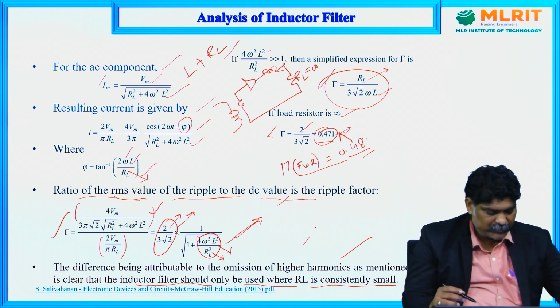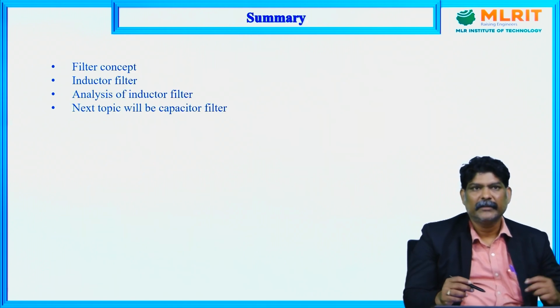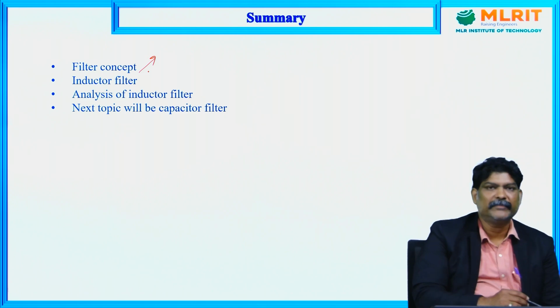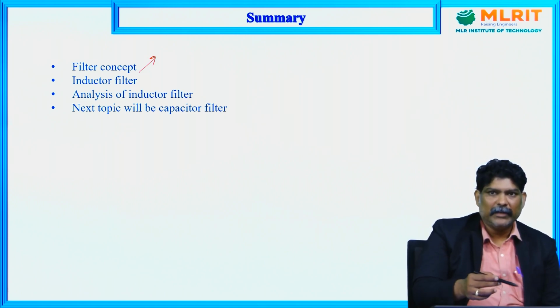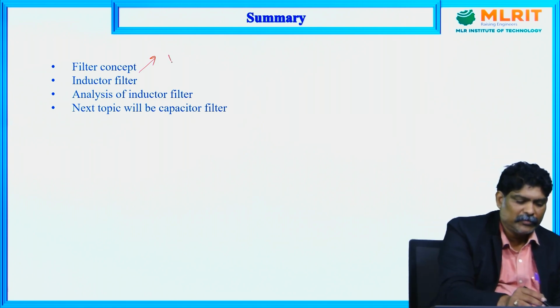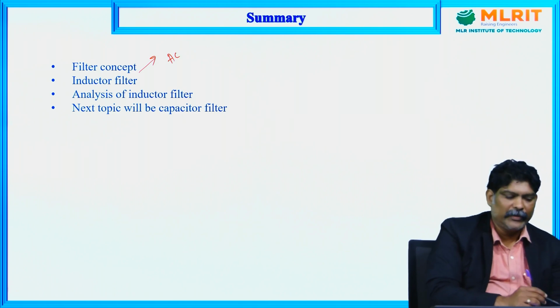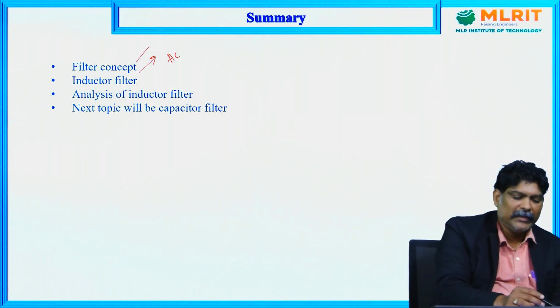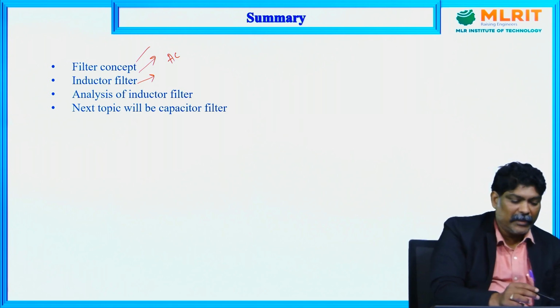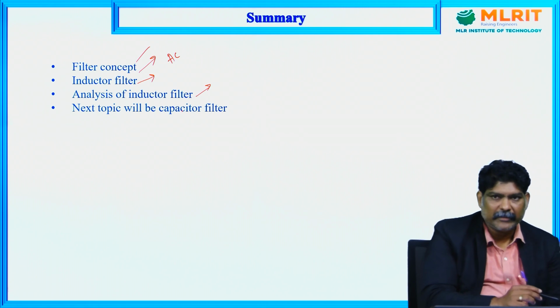So this concludes today's session. Today we have discussed the filter concept, what a filter is, and its importance, because the rectified output has both AC and DC components. To remove the AC component we use a filter circuit, and we have analyzed the inductor filter.